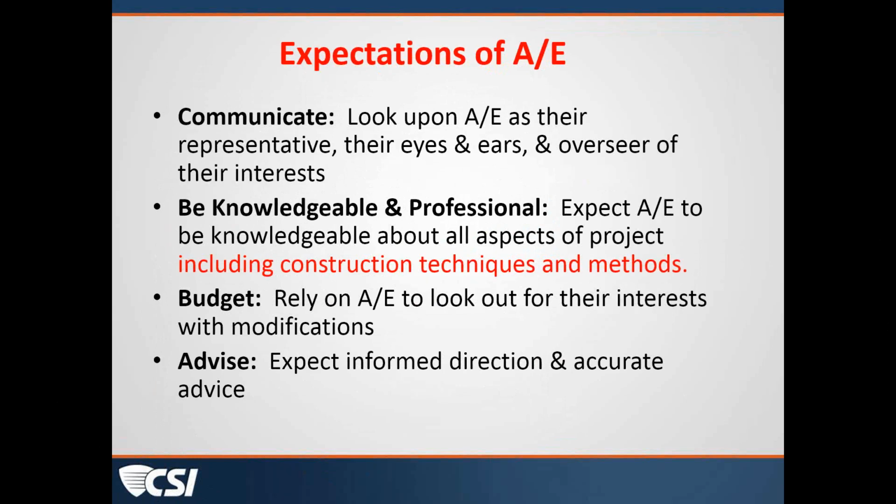I remember one time I was working on a project and the contractor had submitted a question. I went out to the site, we were discussing it, and got back to the office to get with the individual that had worked on this project, whom I needed to help resolve this issue. When I presented it to him, the first thing he said to me was, I was wondering when he was going to ask that question. That just floored me. If you knew there was an issue in the documents, whether it's something that you didn't get a chance to detail or whatever, why would you wait for the question to come to you? There are addendums that can be issued. There are supplemental instructions that can be issued. Go ahead and get the issue resolved before it becomes a problem.